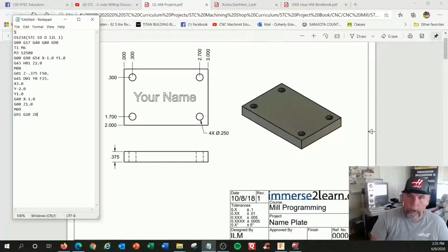G28, Z0. And you might see some funny haha shirts about that. Oh, sorry, I wrote that wrong. G28. Right. The newer one, and I'm going to put in parentheses, anything you put in parentheses is considered to be a comment and not readable by the machine, just readable by us. G53, Z0. G53 means we're switching from the work coordinate positioning system to the machine coordinate positioning system, which happens to be all the way up.